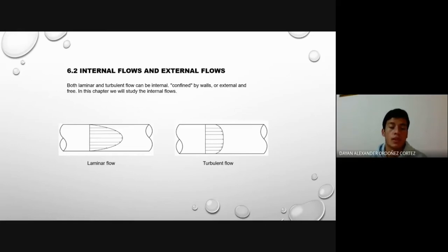The flow in the tube is then completely viscous and the axial velocity is adjusted. The flow is said to be fully developed: the velocity profile is constant, the stress on the walls is constant, and the pressure decreases linearly in both laminar and turbulent flow. Dimensional analysis indicates the Reynolds number is the only parameter that determines the entrance length.